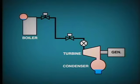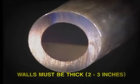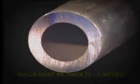The main steam circuit is relatively simple, with one line passing from the boiler outlet to the turbine inlet. For a modern power plant, the steam pressure will probably be within the range of 1,800 to 2,800 psi. In order to withstand this high pressure, the walls of the pipework must be thick, perhaps 2 to 3 inches, depending upon the pipe diameter. Steel alloy materials containing chrome and molybdenum are selected to withstand the stresses imposed by the high temperature operation. A thick layer of heat insulation is placed around the pipe to prevent heat loss to atmosphere.